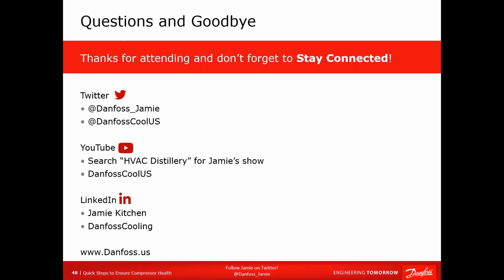If not, fine. But keep in mind that over time, you are going to disturb that winding and it will not last forever. So yes, it's a good Band-Aid solution as a last step. I would not recommend just putting them on anytime you need them, because there's always a cost to that in the form of how much stress you place on the motor winding.